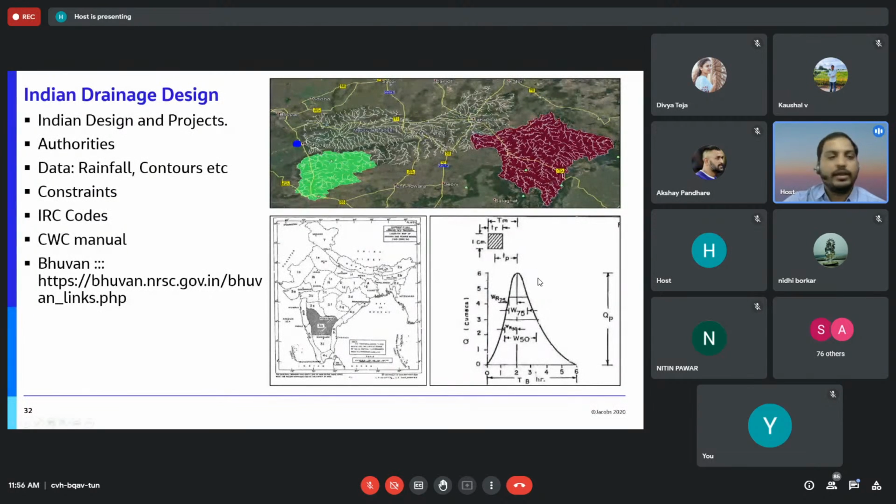With respect to the regions where you are doing your project, here you can see the particular hydrograph we need to take care of when the catchment area is big. Normally we do a synthetic unit hydrograph for 1 mm depth, and there are some input parameters required, and we check the critical time and what the maximum flow is going to be at that particular bridge location, at that culvert location, and we need to design our system accordingly.